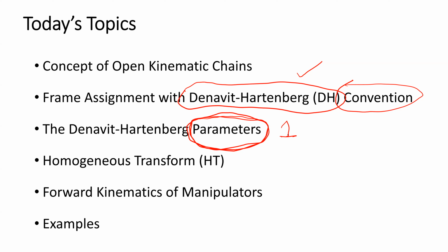We know how we can compose the homogeneous transform from the rotational matrix and the position of the frame origin. Today we just have a short review, but we will see the benefit of the homogeneous transform, and how one matrix of the homogeneous transform can be composed from the parameters of the robot link that represent that link.